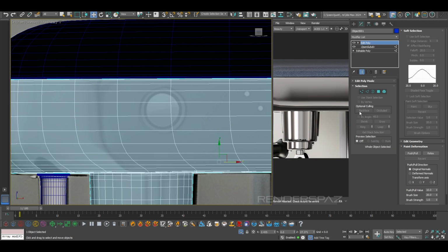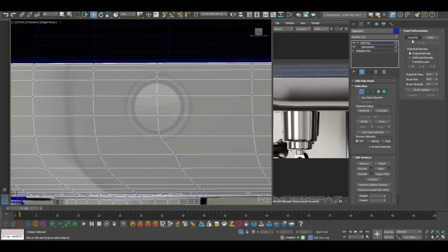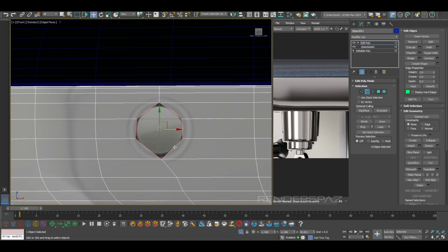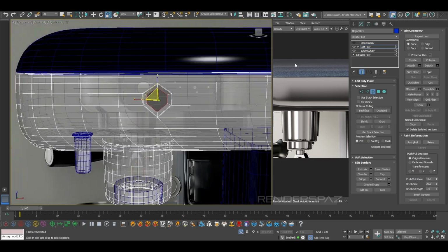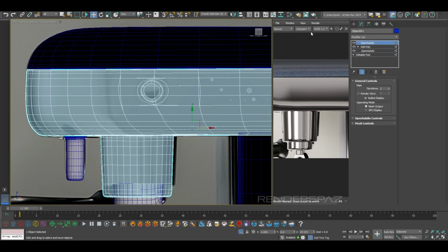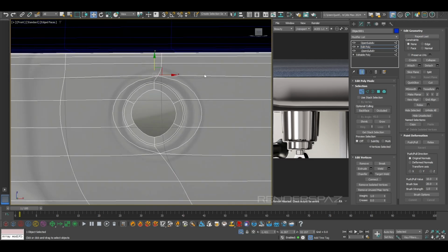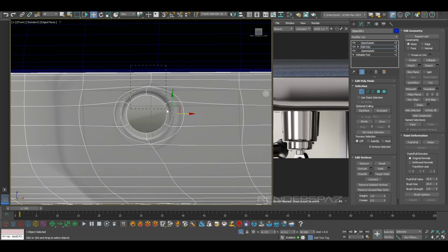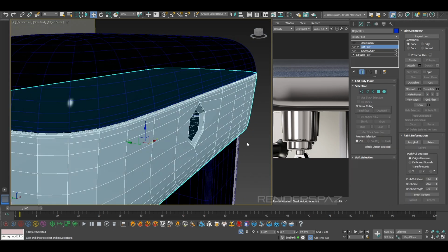let's see here, I'm just going to move the vertices over, and we're going to collapse our open subdivisions, so that we can get some more detail. I'm going to do a manual cut and start to shape out the area where we're going to have that on and off button. What I'm doing here is getting a little bit of a hole going, and we just want to make sure we're uniform with no distortion. So I'm moving things up without creating any bends or anything strange.